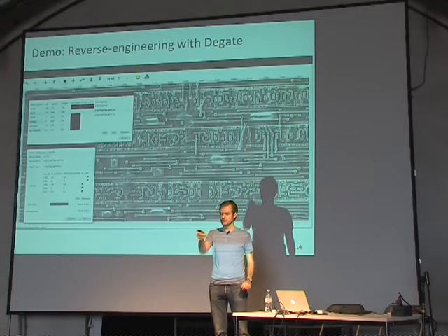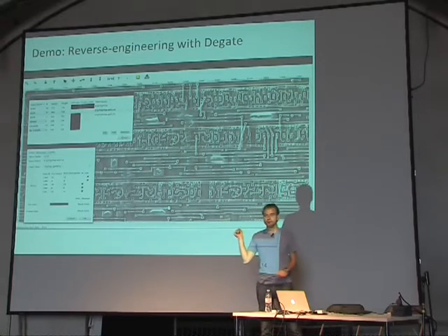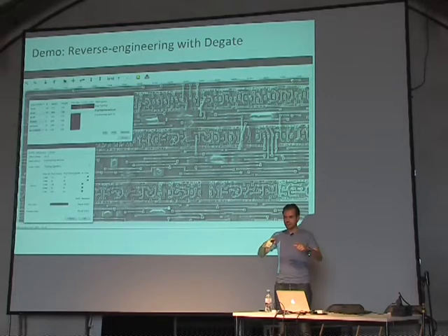And you also asked about the number of layers. There are 2 metal layers that are relevant for the encryption function. There are more metal layers on top, but basically they're functional units. They're routed on the lower layers, and then those functional units are routed amongst each other on higher layers. So let's say 150 pictures.